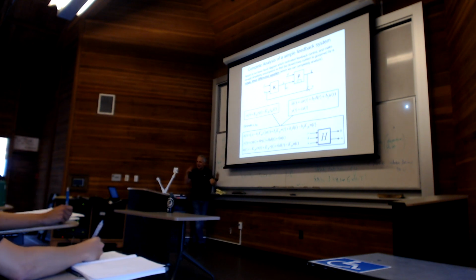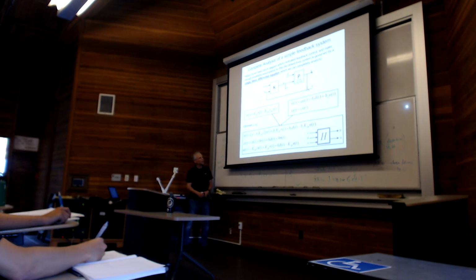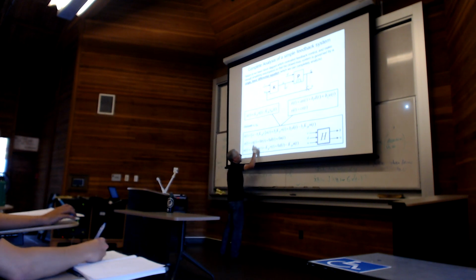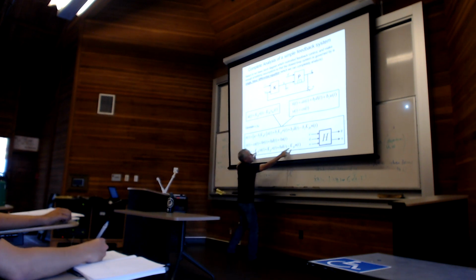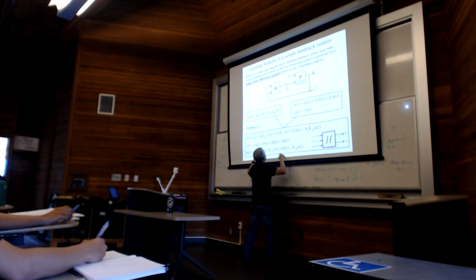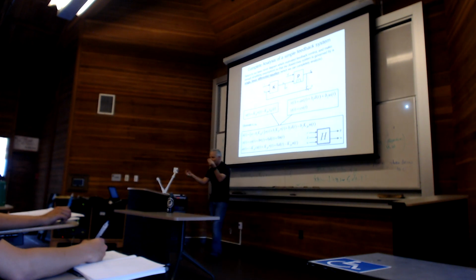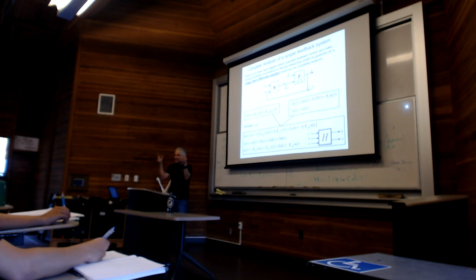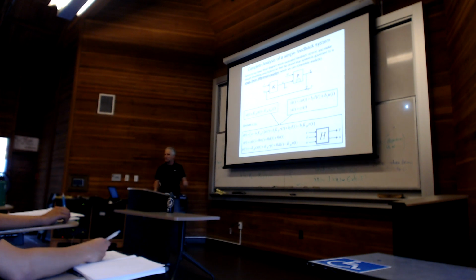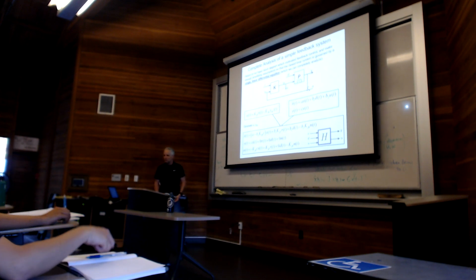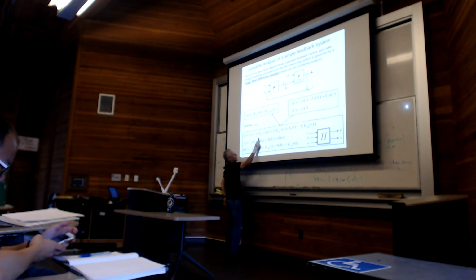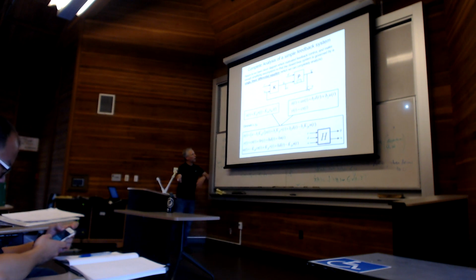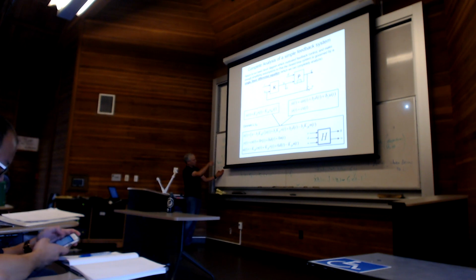So first we have to be able to analyze differential equations. Now we got differential equations that have a couple of things that we can adjust. I can adjust this. The problem is if I adjust this, it also changes there, and there, and there. And I can also adjust this, but that's in several places. So I have to figure out what I am going to do with these 2 degrees of freedom in order to make the system behave the way I want it to behave. So now we have to figure out how this thing behaves, and why would we set KFB to be, for instance, 4 or so on, positive 5 in this case, right? The minus sign is built into the formula.